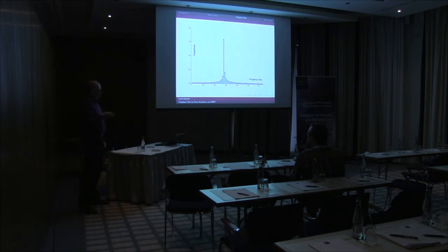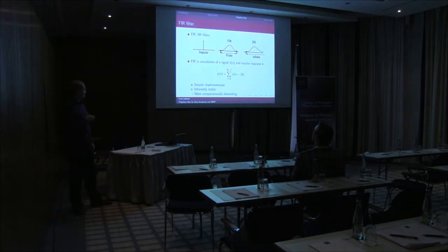So when we apply the polyphase filter, we get something like this. So we get a clear peak, but the DFT leakage is still there, but it's very suppressed. You can see it's from about 6 something here in magnitude, and noise generated by DFT leakage is about 0.010. So polyphase filter is good.